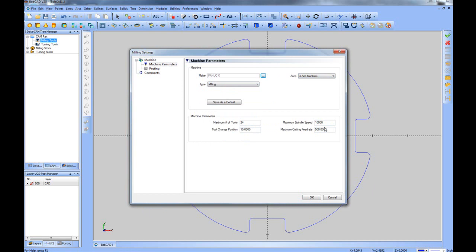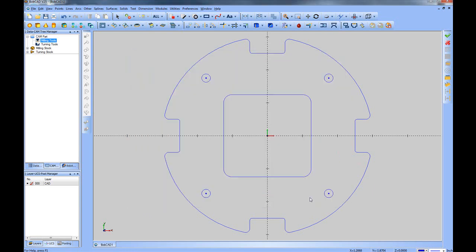And we've already set up our spindle feeds and our feed rates, so we should be good at this point. We'll go ahead and choose OK. Now this just selected which post processor is going to be used, and also several other options for this program. And that can be changed at any time after programming as well, and then the G-code will update for that machine.